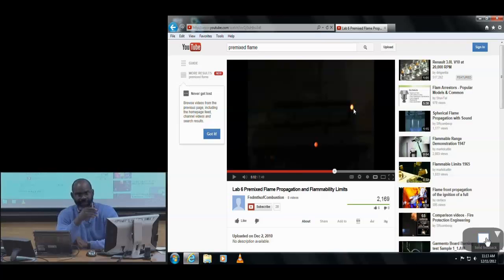So when you look at high temperatures, the types of temperatures that you have in a combustion system at normal pressure and gravitational conditions, you get buoyant velocities on the order of 5 to 10 centimeters per second. As you look at flame speeds for the weakest mixtures that you could possibly ignite, all of a sudden they're starting to be comparable, and so you see a distinct leaning and buoyancy-induced flow artifact to the flame as it propagates across.